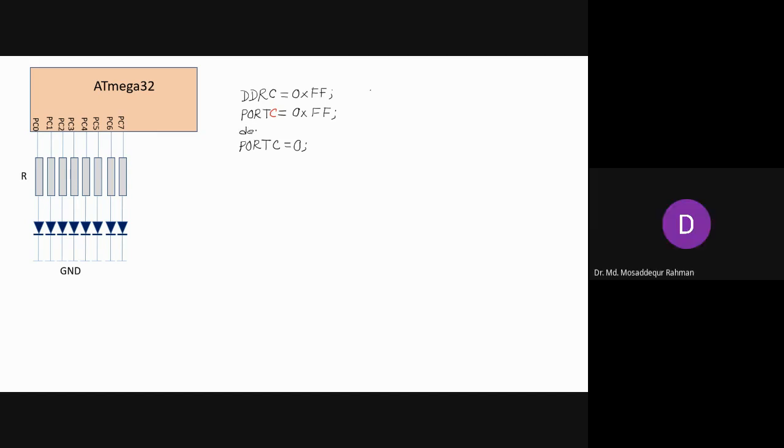So some special tool will be needed. So we need to introduce some delay in between. Let's say 1000 milliseconds is 1 second. So it will remain on for 1 second, then it will turn off. Right? Now, if you want to repeat this action, what modification do we need to do?